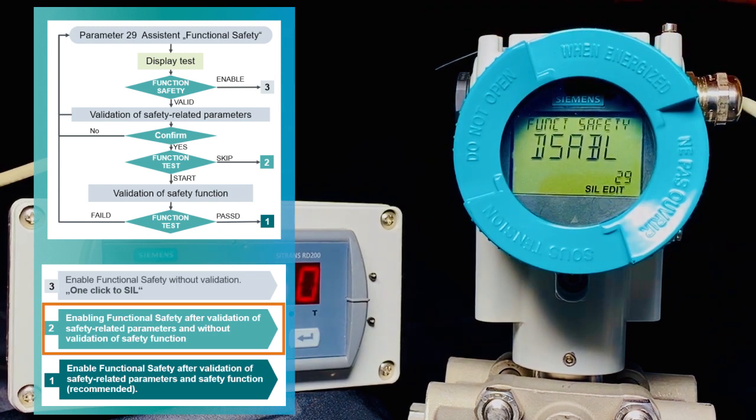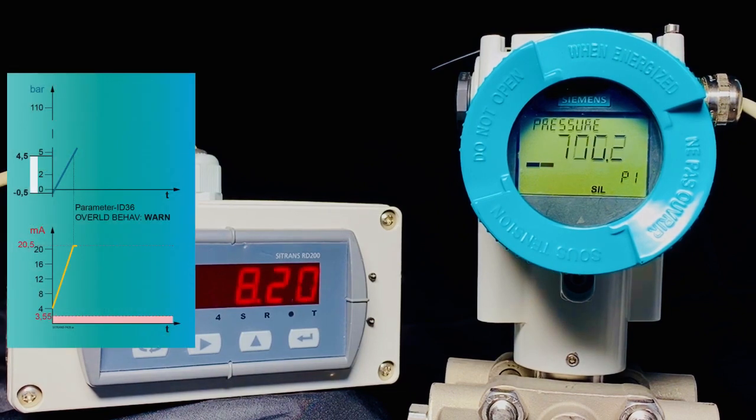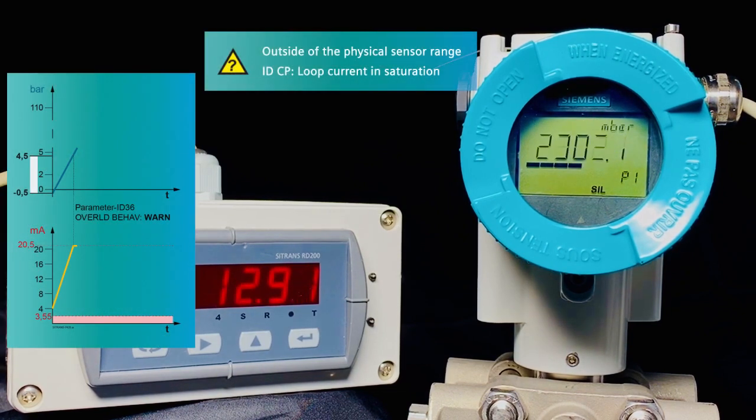We switch to the measurement view with the left arrow button. The SIL symbol appears on the display. As before, we increase the pressure and the NE107 symbol triangle with question mark appears. Under Info appears CP, the output current is in saturation. If I increase the pressure further, the diagnostic message changes to CU. This means PV status uncertain.